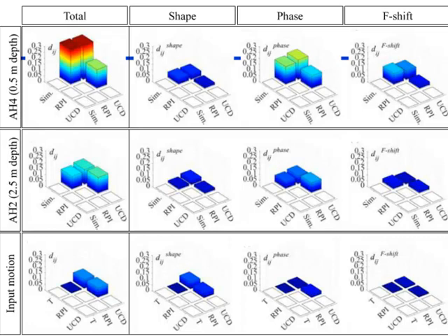Near the surface, the discrepancy between the model prediction and the recorded motions is larger than the discrepancy between the recorded motions. So that means the prediction at this level is not as good as the one, let's say, at 2.5 meter depth. And the decomposition of the discrepancy shows that the contribution is coming mostly from phase dissimilarities. Is this a sensitivity issue, or does the model need improvement? For instance, the damping mechanisms may not be appropriate.